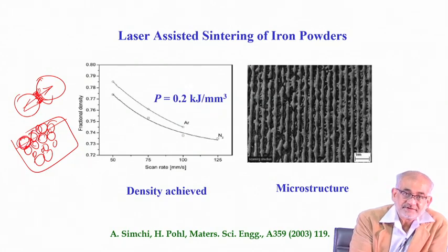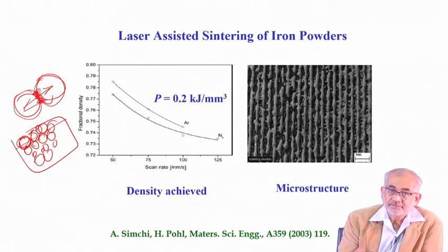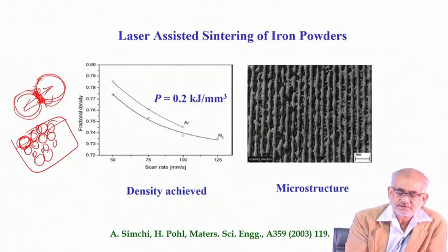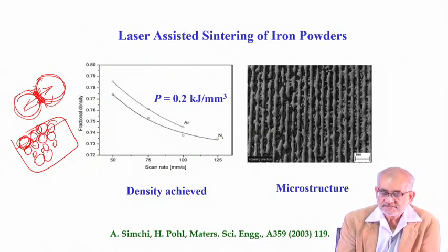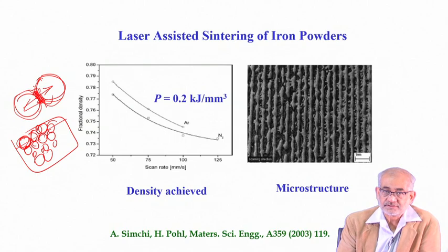So the heating effect will be maximum at the surface, and hence the powder particles will get heated up such a way that a thin layer from the surface reaches fairly high temperature that will allow diffusional bonding to form. So it can be solid state, it can be also formation of thin molten layer, and so liquid phase sintering, and this thin layer may form because of certain reaction, eutectic reaction at the surface. So no matter what, using laser, one can start with powder particles and then sinter and create a base, a bulk solid, the density of which could be close to the theoretical density.